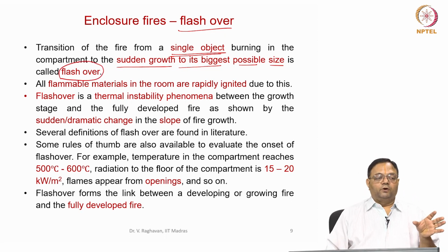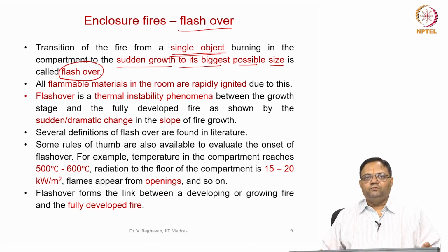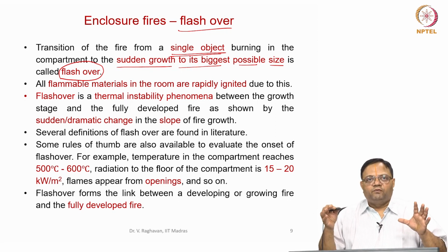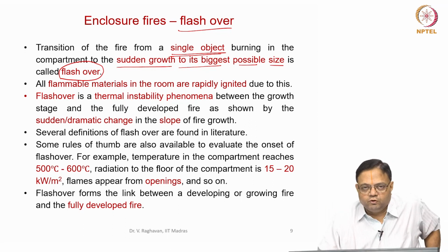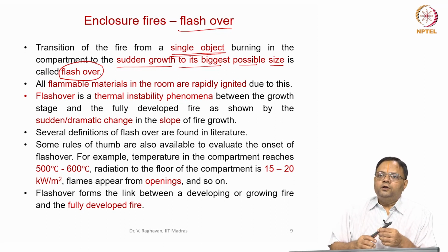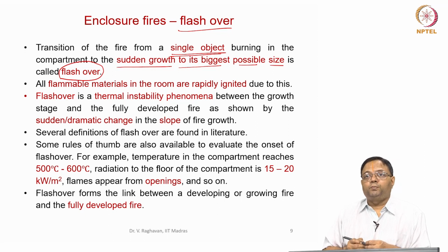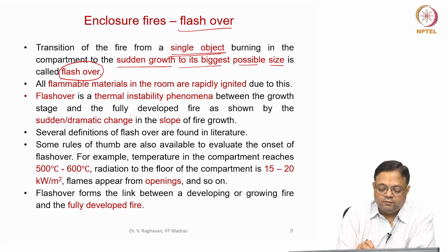So if initially a single object is burning, if you don't control it, then it may ignite other commodities after its growth to some stage, where you will see the biggest possible fire in the enclosure. So when the single commodity or single object is burning, you will see that there will not be much effect. But once all the commodities in the room burn, that will lead to the formation of the biggest possible fire. So that is actually termed as flashover.